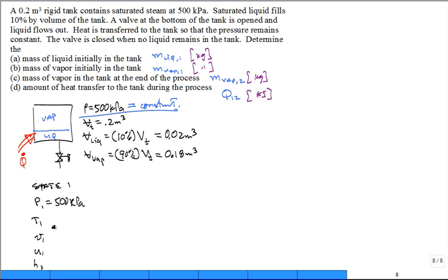All right, what about the temperature at state 1? If it wasn't explicitly given to me, can I deduce it? Okay, and what is it? You did your part, you said yes, now let somebody else shine. And they can now give it to us. What is it? Oh, it's just a correlated pressure. It's the saturation pressure for that substance, steam, at the 500 kPa. It's 152 degrees C? 151.9. Close enough, 152. All right.